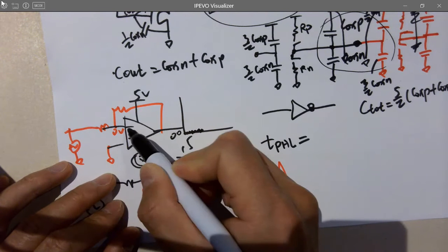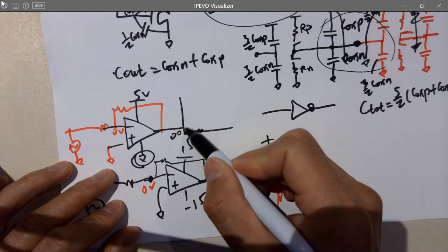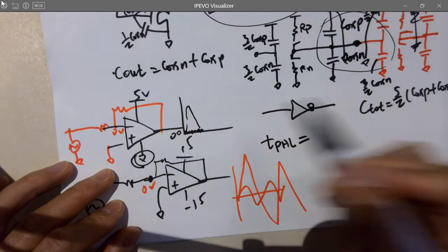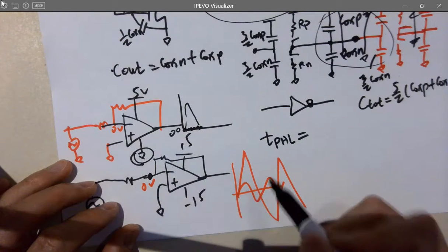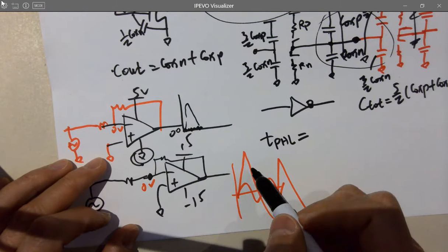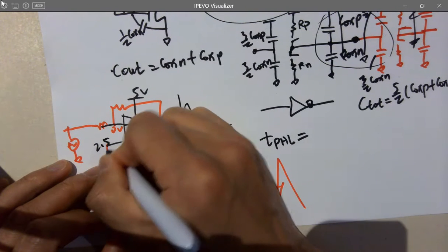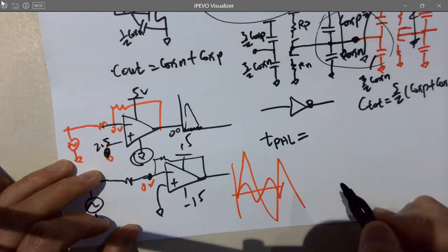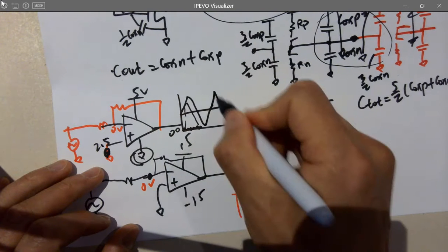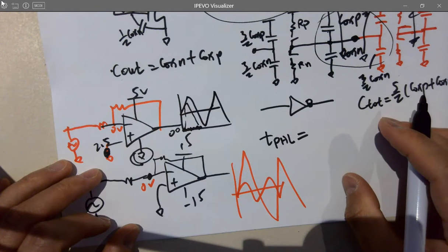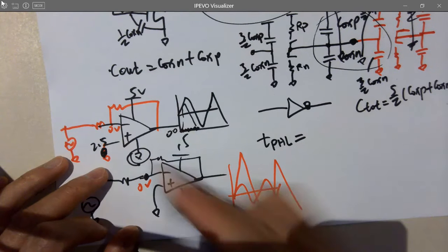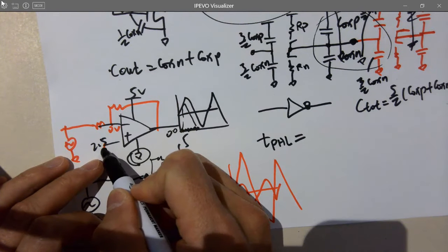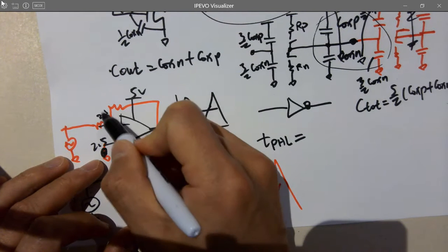You got an AC swing. It is able to swing upwards, but downwards, forget about it. It will never happen. So how do you want to do it here? Lift it up to 2.5 so you can swing it. Make sense? Superposition. You're getting a 2.5, so this point will be permanent 2.5 DC.